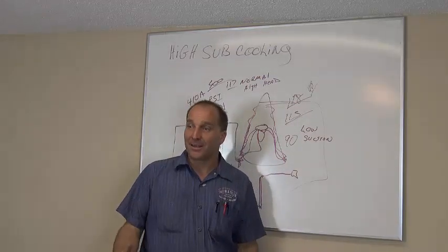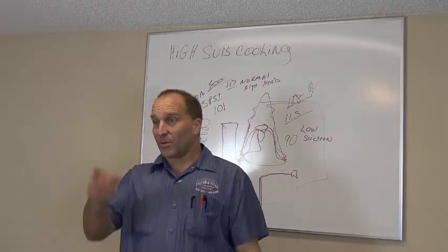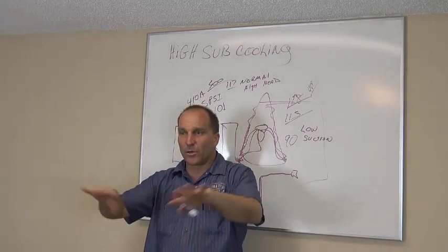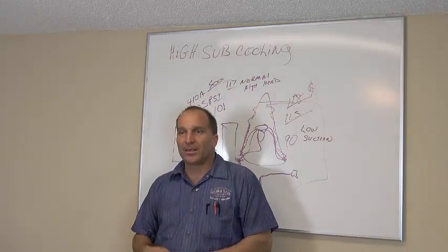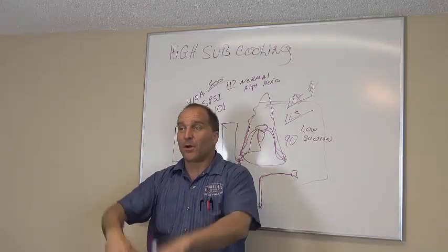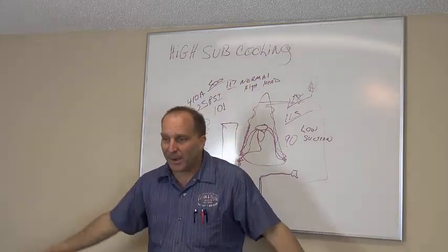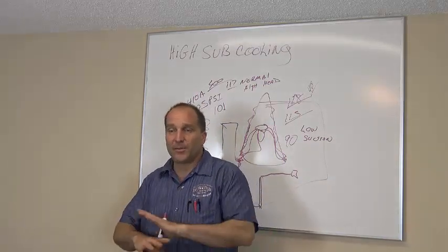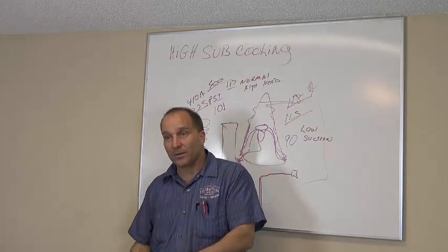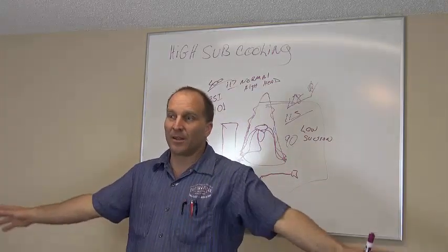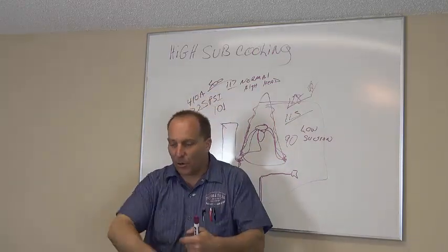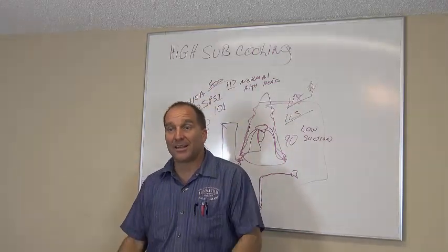Let me tell you what a clean condenser looks like. When I'm walking up to the condenser and I look at it from this far away, it's clean. The slab is clean around it. There's no dirt and leaves around it. So if you get to that system and you've got an oak tree sitting over the top of it, and it's dumped all the leaves inside the condenser, and it's piled up around it, and it's got concrete around it, and these people don't maintain their house properly, when you leave that system, you see the concrete because you've hosed everything around it, and now the water can drain out of the system. You've pulled all the leaves out of the inside of it, you hosed the inside of it, and it's clean. That is a clean condenser.